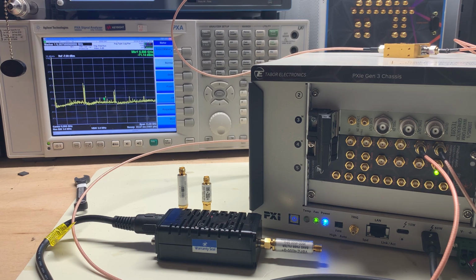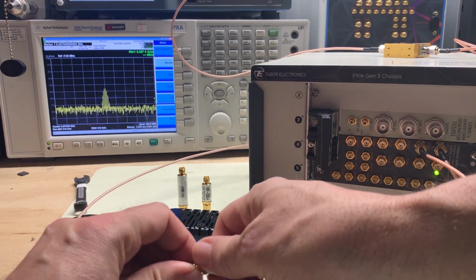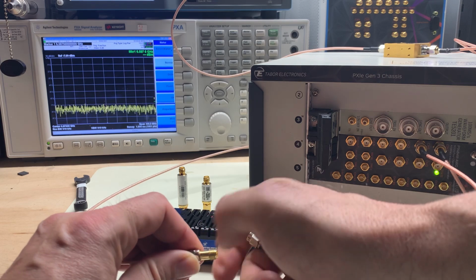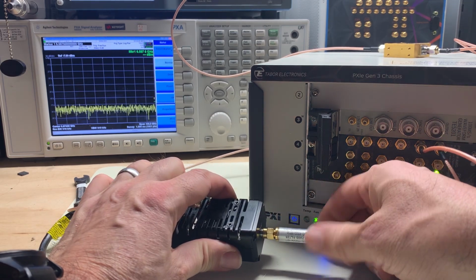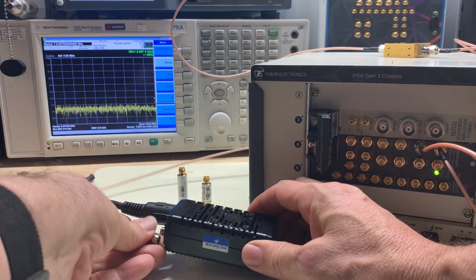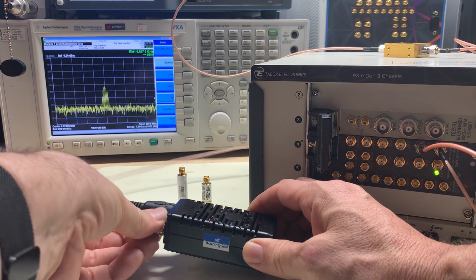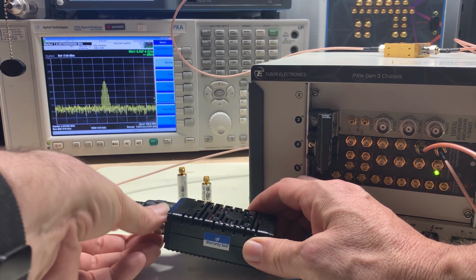So one of the things that we advise, or we've concentrated on, is to use an amplifier. I have this amplifier here, the 10200, which goes all the way up to 20 gigahertz. It's got 1 watt of output power, that's 30 dBm, so its P1dB is pretty high, and you can drive it pretty hard.